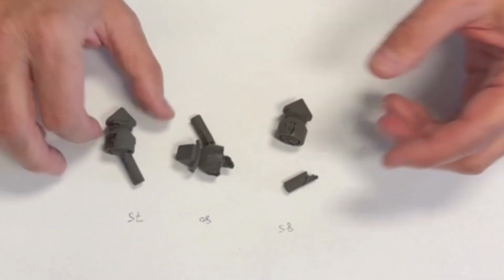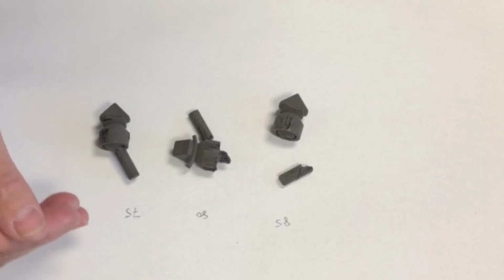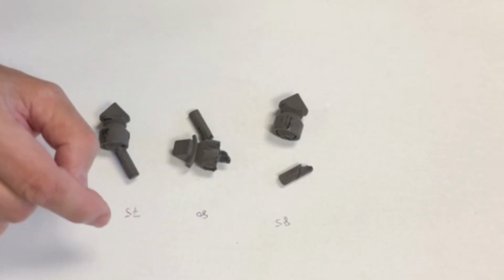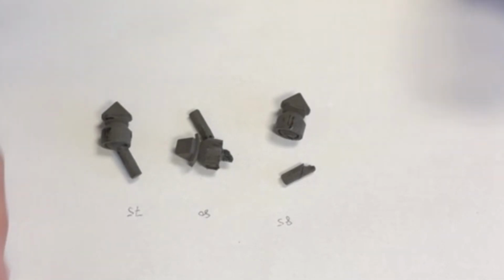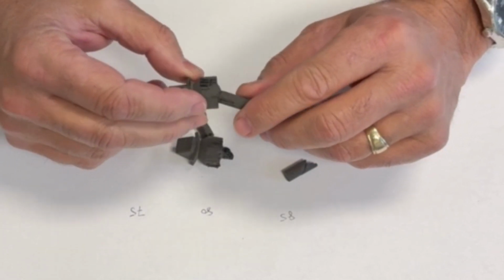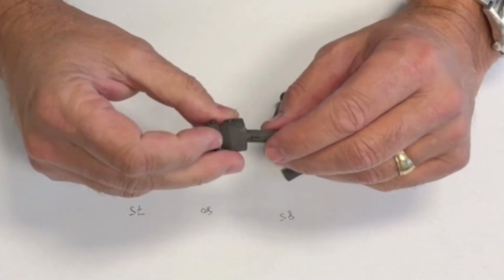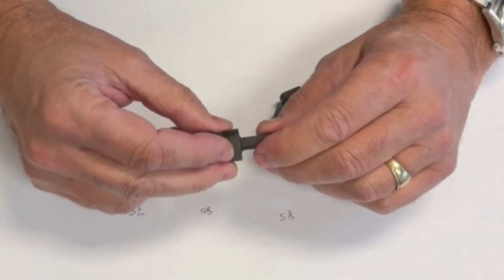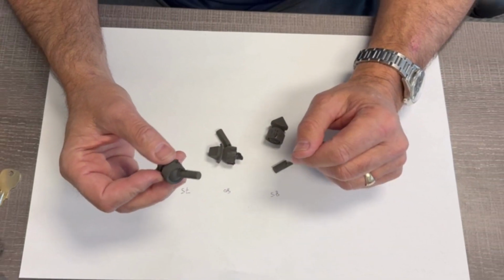So I'm beginning to think that I need to run all my future prints at 75% of the default energy density, and that includes the fill and the outlines, to really maintain the tolerances that I need between parts and still keep the overall strength and integrity. So I'm going to do some tensile bar prints and really see if there's any drop off in mechanical properties. I don't have a tensile machine, so I may have to rig something up.